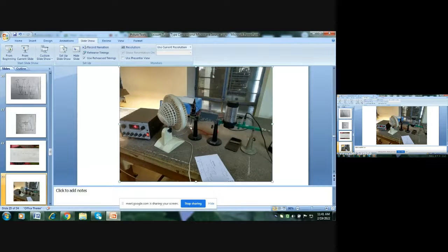So when you perform the experiment, be sure that the impedance of the Klystron mounted in the mount at a point should be equal to the impedance of the waveguide at this point.